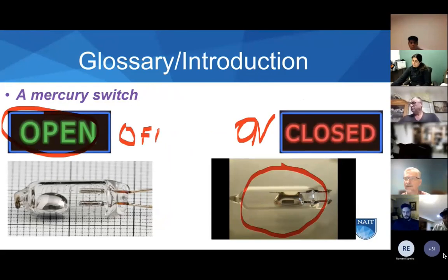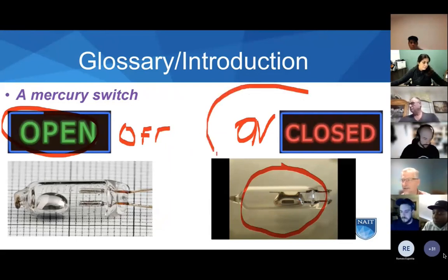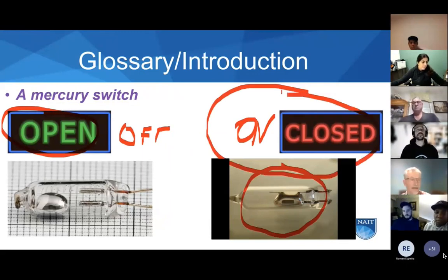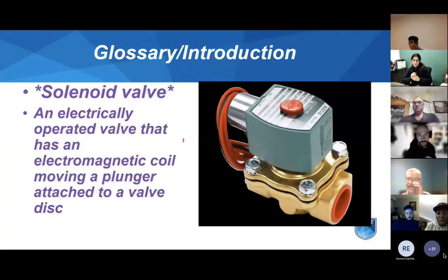Okay, if this switch is closed like it is on the right, the gas valve will be energized and fuel will flow. When fuel is flowing, we need to ignite it. When we ignite the fuel, we want this to stay in the closed position, and it would only go over to the open position if something goes wrong.